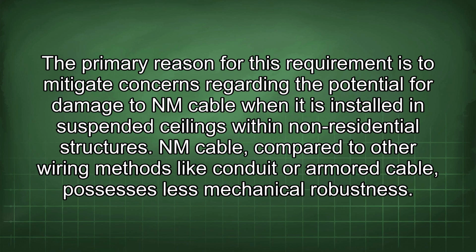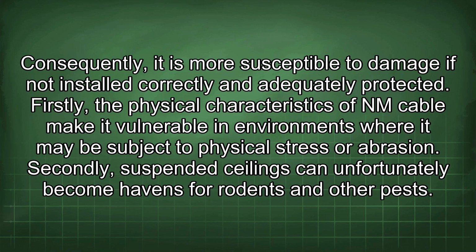NM cable, compared to other wiring methods like conduit or armored cable, possesses less mechanical robustness. Consequently, it is more susceptible to damage if not installed correctly and adequately protected. Firstly, the physical characteristics of NM cable make it vulnerable in environments where it may be subject to physical stress or abrasion.